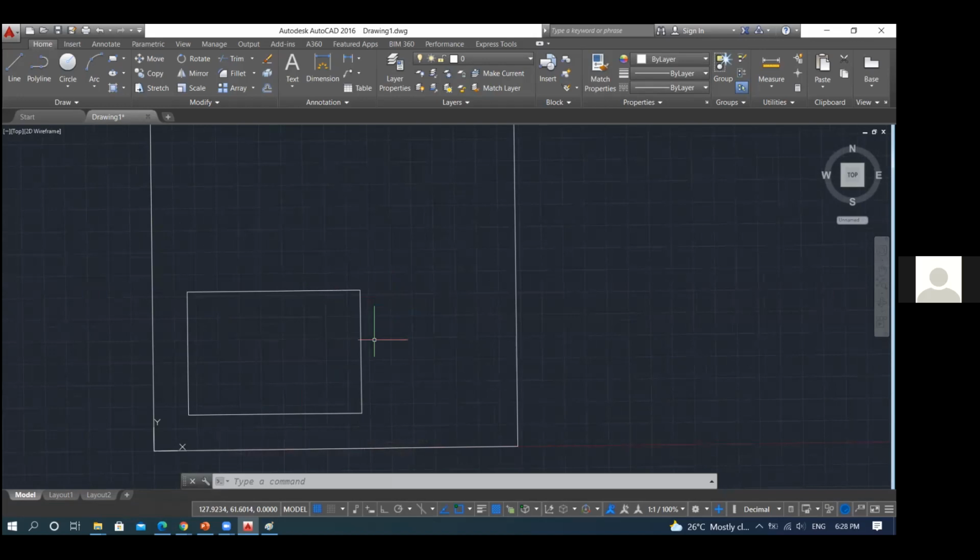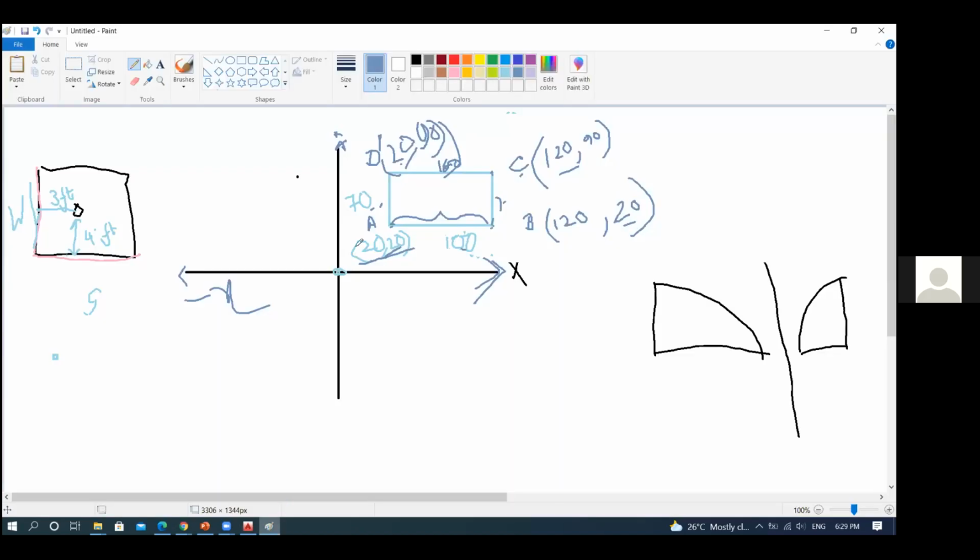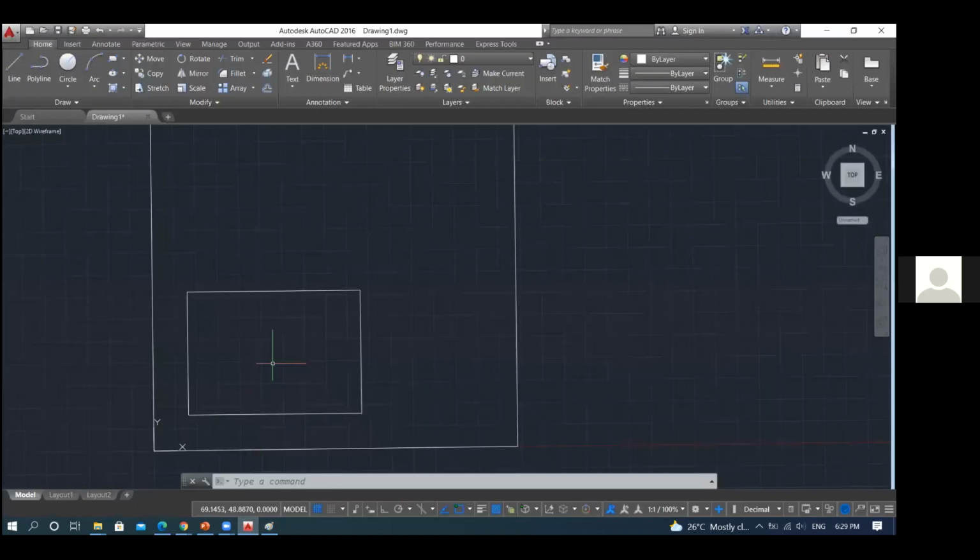Now in this manner you can draw a rectangle. So what are the steps? Firstly, you have to draw a rectangle using pen on paper for the beginning period. Then one coordinate is given, and length and width are given. You have to assign the value of other coordinates or other points of the rectangle. After assigning this, you can simply draw this by using line command in this manner. This is the use of simple Cartesian coordinates. You can draw a rectangle easily. Okay.